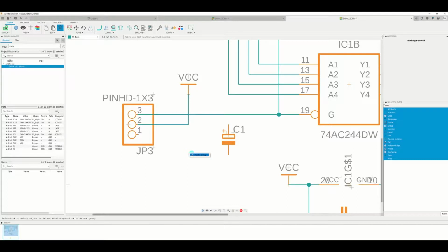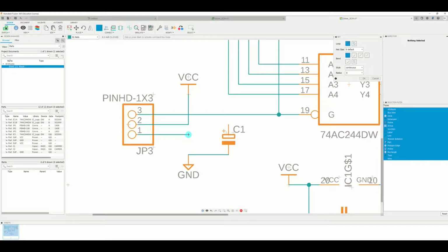Then you move this down, click the component. Sorry, we have deleted the whole group. We can undo it here. So that's it. Then move it, then click the handle, and then move it down until this is aligned. Then we select connect the net, click here, connect, and then click this one, and then connect, and then we connect this to this one.